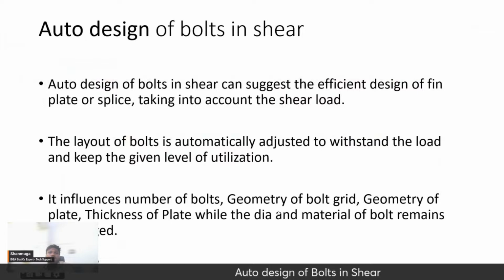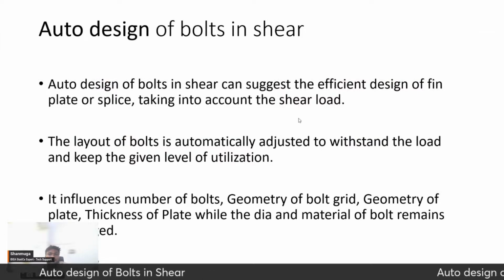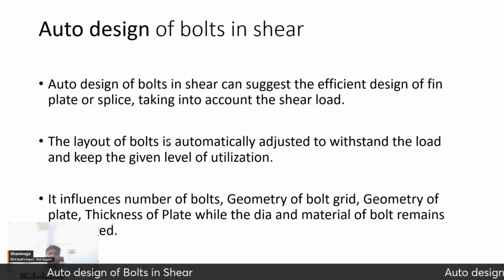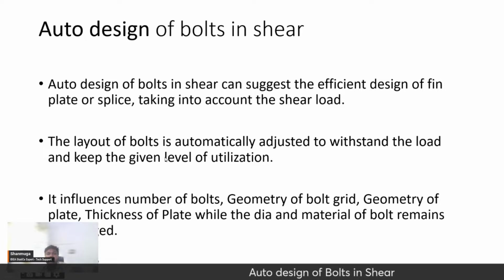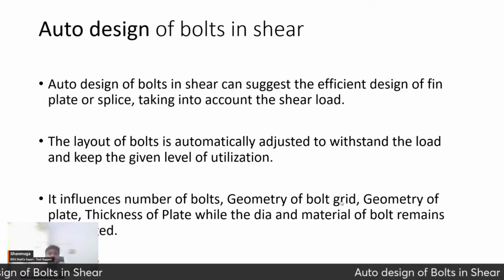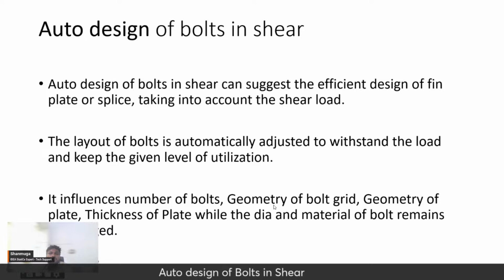As an explanation of auto design of bolts in shear, we can see here it can suggest the efficient design of fin plate or the splicing arrangement, taking into account the shear load. The layout of bolts is automatically adjusted to withstand the load and keep the given level of utilization. It influences the number of bolts, geometry of bolt grid, geometry of plate, thickness of plate, while the diameter and the material of the bolt remain unchanged.